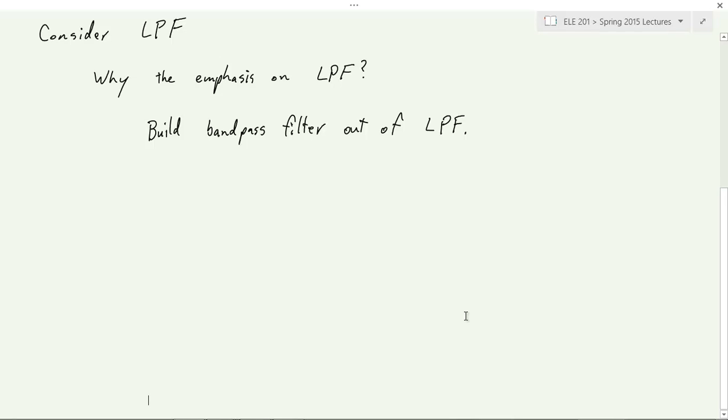If we think back to the convolution rule, the modulation rule. Suppose you have some low-pass filter like this with an impulse response, and suppose you multiply it by a cosine, so you just modulate it. Okay, then this, of course, is going to be convolution in frequency.